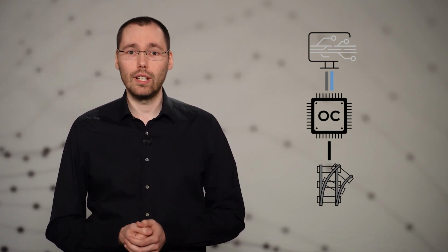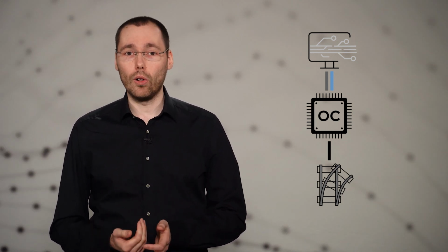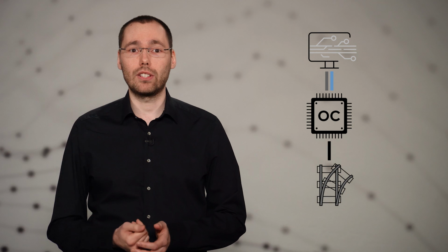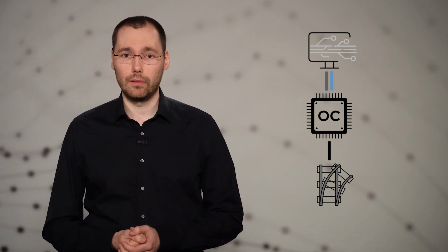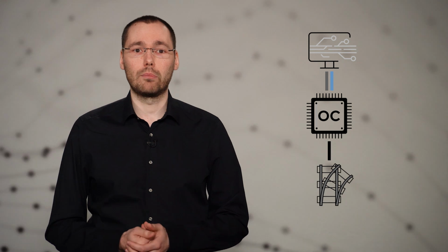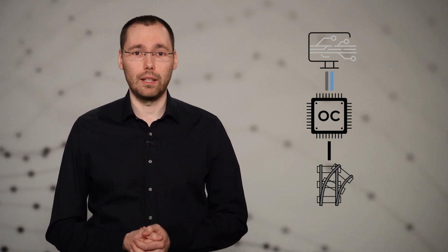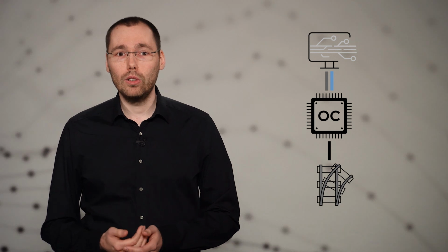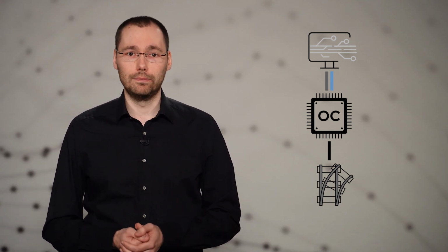First and foremost, debugging is much easier in a virtual environment. Also, the code can be adapted much quicker, as it does not require flashing the software to the microcontroller. Furthermore, this approach does not require every developer to have a physical device with them. Overall, we achieve improved modularity and easier maintenance with SIL.